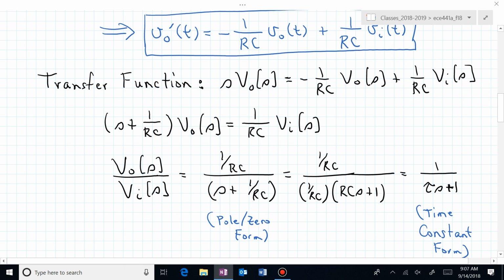Or what that means is normalizing that constant coefficient in the denominator's factors to 1. And then what's multiplying the s, in this case a first order, that tau is our time constant, and whatever is floating upstairs is our DC gain, or the gain of the transfer function. The DC gain, the gain at low frequencies, in this particular case is that transfer function evaluated at s equals 0. If we plug in s equals 0, what do we get on the right-hand side?